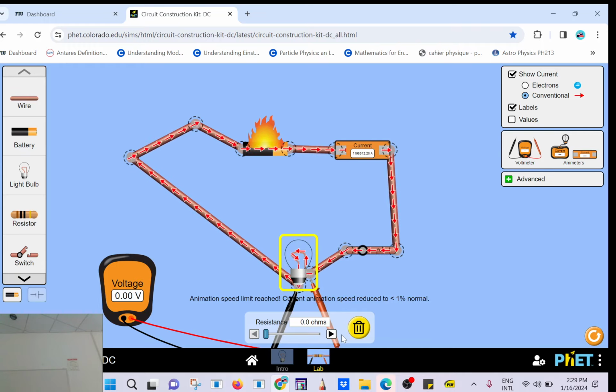Can you see that? It's about 2.5, right? So it's taking away even more voltage because the voltage drop is proportional to the resistance. So this one is crying because you see it doesn't get enough voltage. Now it's like 1 volt.